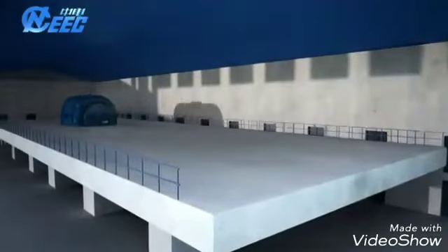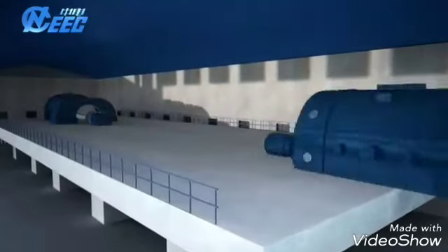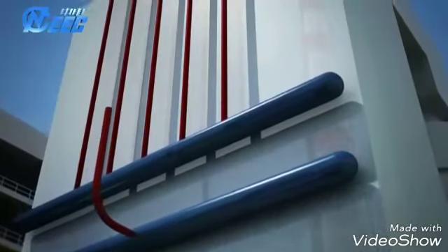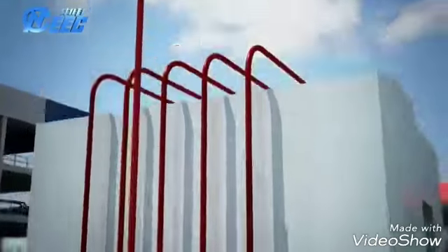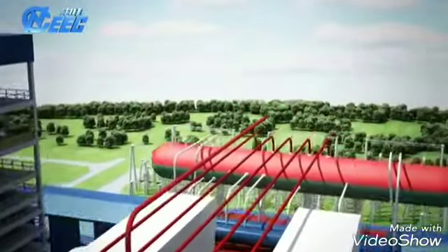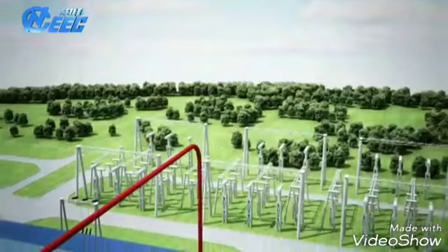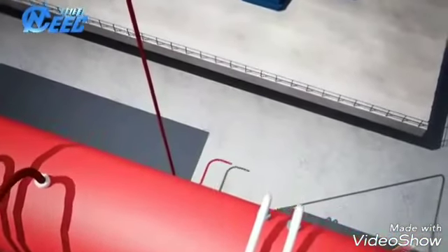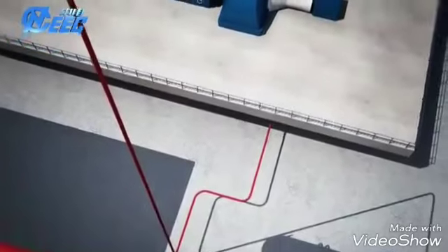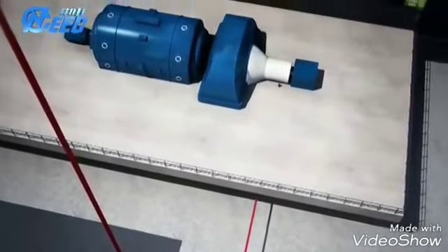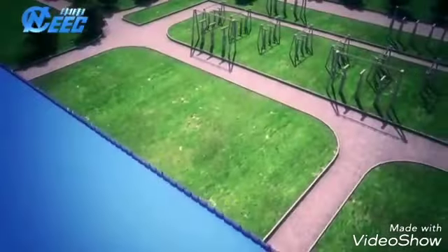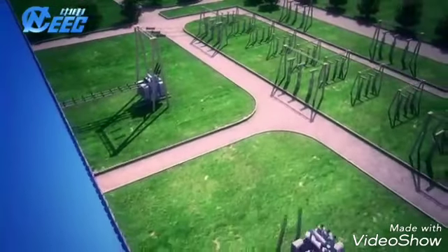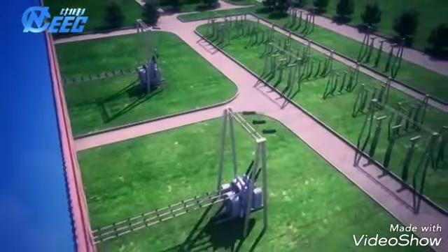Steam turbine used in this power plant is of condensing type, and the generator is air-cooled with a brushless excitation system. The main transformer is oil-immersed and air-cooled type, and the electrical wiring is in double loops.